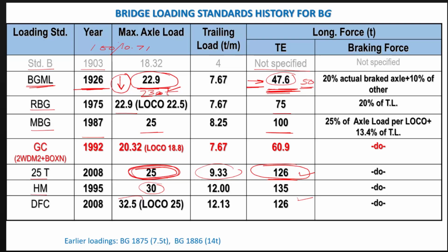Like if we are designing new bridges, normally our major component is the longitudinal force. Transverse force is very less. It is like wind or seismic case only. So the major component is the longitudinal force, and for the longitudinal force we are designing our structure width and so on as a new structure.